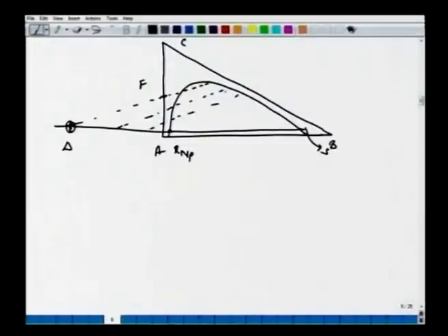But in some systems it's possible that certain tie lines are like this, which means if you extend them, they will be intersecting this line or this curve further away from this R and P. So in these cases we must choose that intersection, that del difference, which is farthest away from R and P. In other words, one is supposed to extend all the tie lines which intersect this line connecting R and P and S, and pick the one furthest away from R and P.